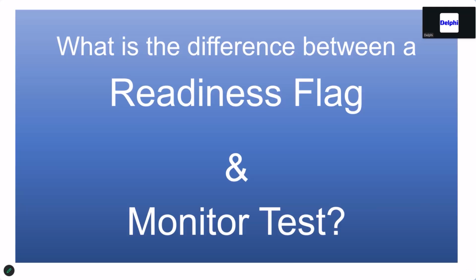Okay, another thing I want to clear up is the difference between a readiness flag and a monitor test. Readiness flags are what we use for emissions inspections. That's also what we use to know if the system is done testing. So if it's catalytic converter and it says complete, it's telling us in 2008 and newer, we are done testing the system. If there's no MIL, no pending code, then the system has passed. The thing is, though, those are not monitor tests. Those monitor tests make up readiness.